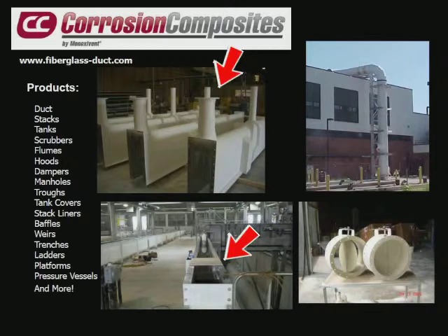There are 8 grit flumes used in grit removal, and they're about 200 feet long. They had to be abrasion resistant, and they had to be perfectly level on top and sloped from 18 inches on the shallow end to 36 on the deep end. All of the drains, overflows, etc. had to fall within the very tight tolerance for width. If you look at the lower photo, you'll see the large traveling bridge that moves along the side of the trough, and everything had to clear.